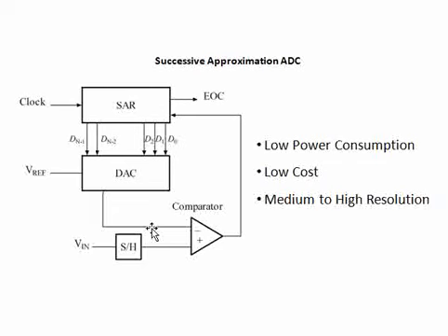So three things here. One is basically the DAC output, the performance of the DAC, and the successive approximation register type, where the output is depending on the comparator stage. So these two are the very, very important points that we need to remember in successive approximation. It's a little advanced ADC conversion other than the normal, simple ADCs which are there.